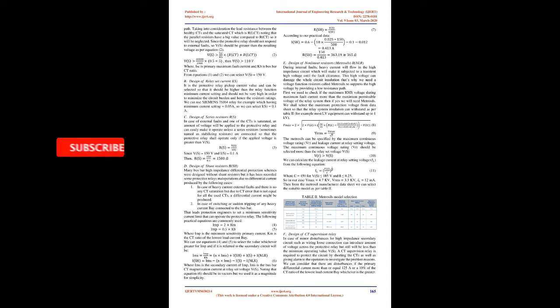path. Taking into consideration the lead resistance between the healthy CTs and the saturated CT, which is R_LCT, noting that the parallel resistors have a big value compared to R_CT, so they will be neglected.